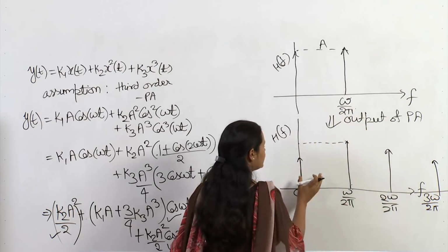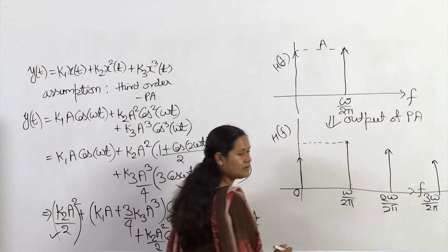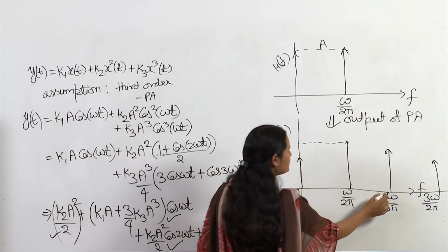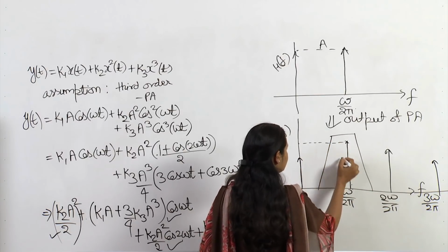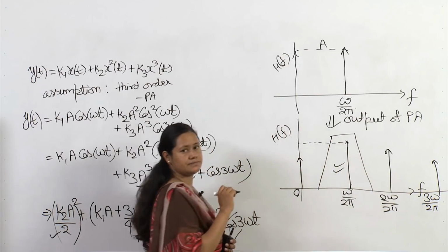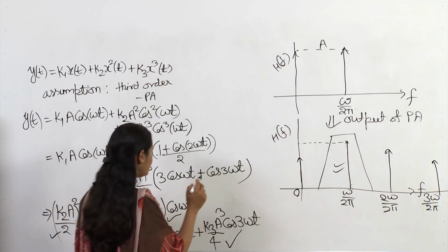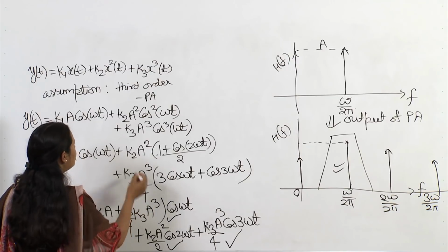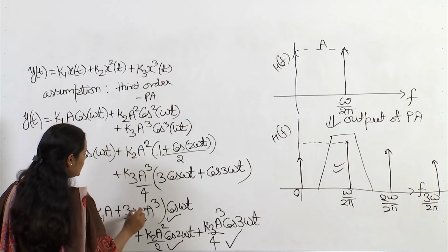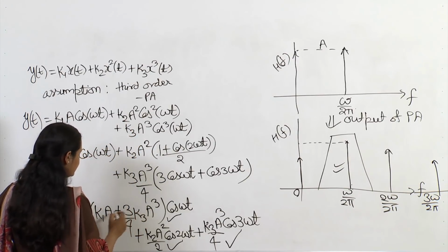So for one signal in the frequency domain we will see more than one component. Now, these components are very far, so you can say okay, we will filter it out and we can take this signal, but still if you look at this, our output is not an exact replica of our input, basically it has some extra terms here.